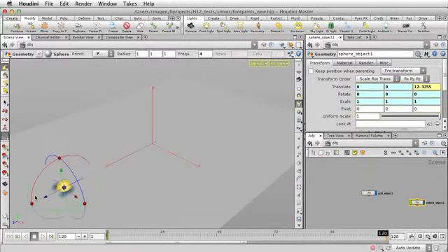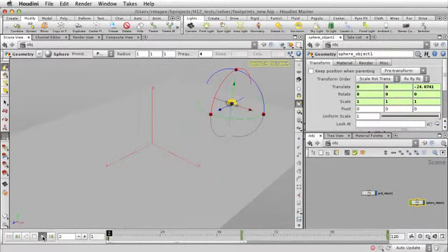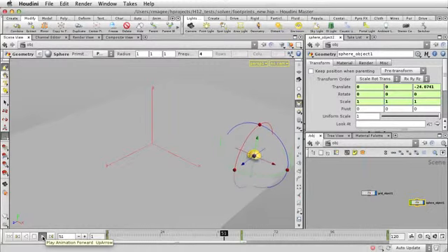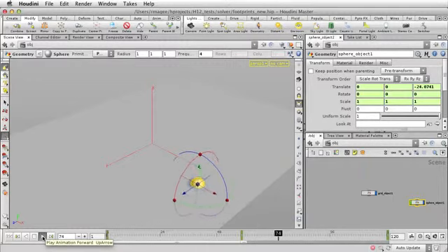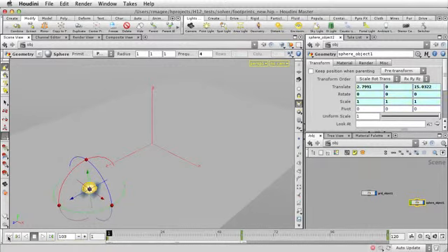And what we're going to show you is that not only does this update when you move it, but it'll also update if there's any animation. So the procedural nature of Houdini sort of holds true during an animation. So if we press play, you'll see that the attribute transfer is working on a frame-by-frame basis, and we're transferring the attributes. Now the thing is that we don't want to just transfer it and then have it forget what happened. We want to leave a trail of all the places where this attribute transfer has occurred.